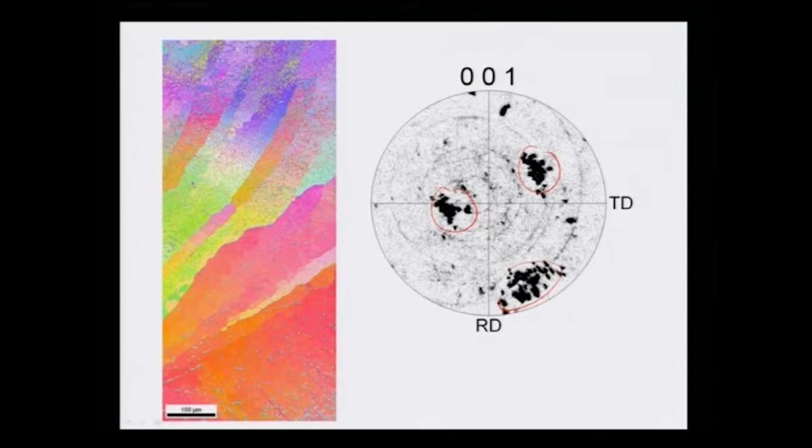As you can see, the largest cluster is coming here, which is at an angle almost like 90 degrees from the pole, and some of these are coming at around 111. Okay, this is close to 111. Those of you who know a little bit of this will understand. So, therefore, we can obtain the majority crystal orientation from these images, which is very nice, and the inverse pole figure of this will be this image.